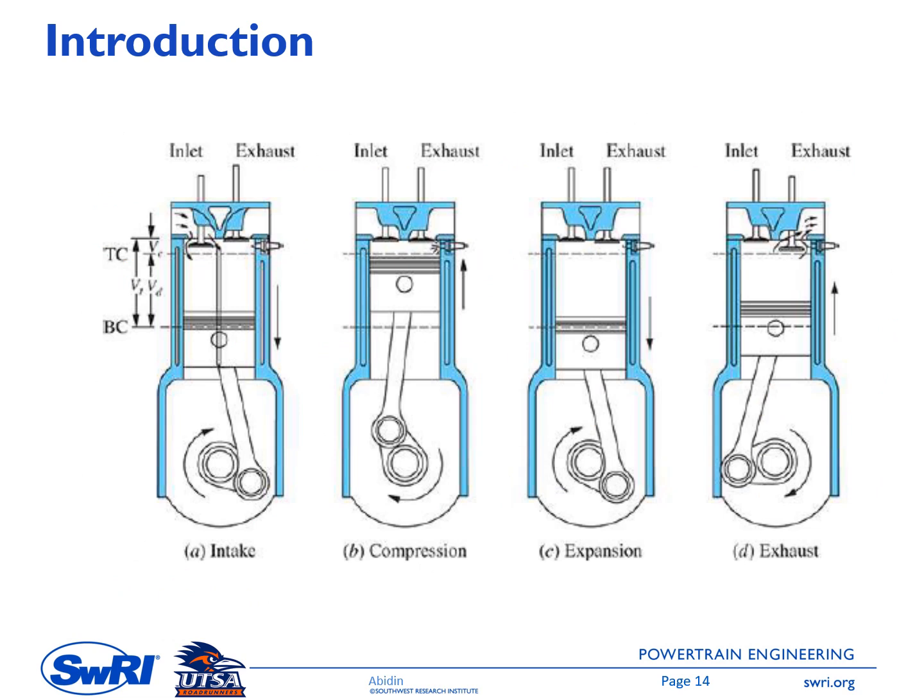Okay, this is a schematic of the 4-stroke process. So we have an intake process here, the fresh mixture entering the combustion chamber. So this is the combustion chamber, okay? And then this process ends when the piston hits bottom center at this one, okay?